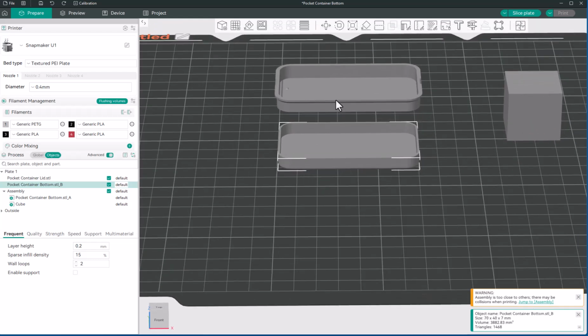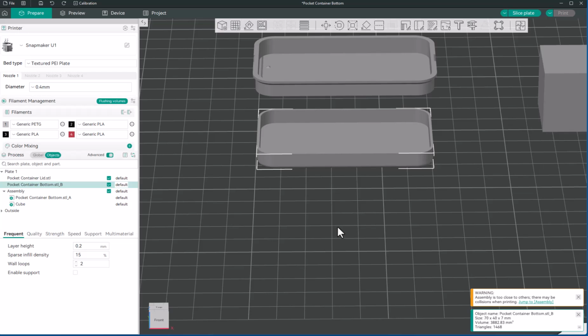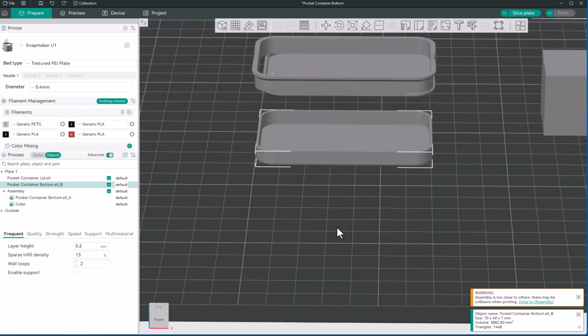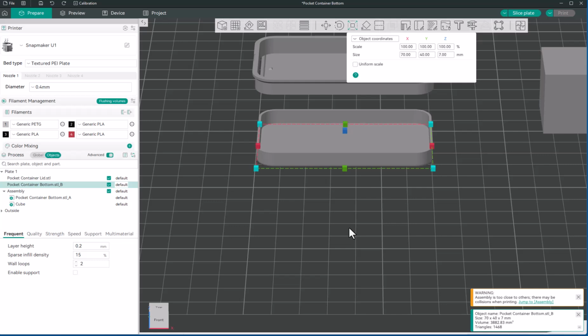Remember I was saying how bad it is to scale? There's nothing that's going to hurt scaling B when I do this, there's no lips or anything on it to matter. So I'm going to go here, and right now it's at 7 millimeters tall. I want to get to 40. So we'd have to add 33 to 7 to get to 40. So we're going to scale up. I'm just going to put 33 here.